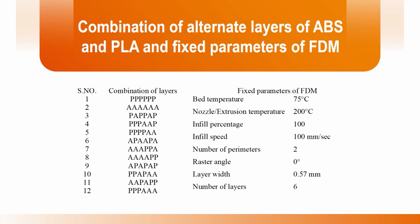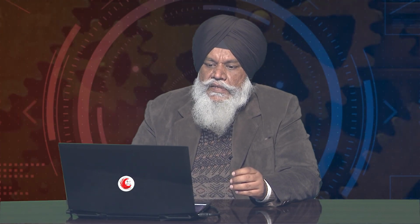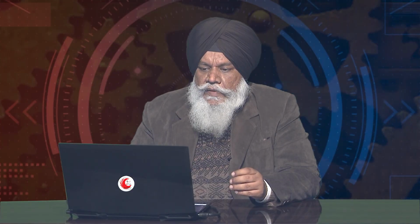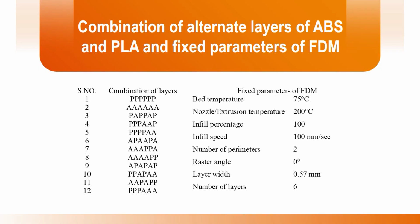What we have done is we have fixed the bed temperature, nozzle temperature, infill percentage, infill speed, number of perimeters, raster angle, layer width, and number of layers. These have been kept constant for this investigation. We used the concept of random numbers, and by fixing the number of layers as 6, we chose around 12 combinations. This was just at random to understand the effect of the different layer combinations on the final quality of the product.